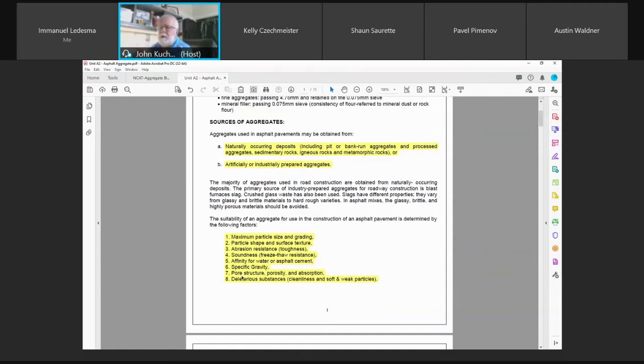In Winnipeg here, we do a lot of thin lift asphalt overlays. In other words, we peel off what we have that's on the concrete. Okay, we fix up the joints, and then we put the asphalt back in. So we're limited, maybe 60 millimeters. And that's why the type 1A mix that we're looking at is nominal size of 16 millimeter because of the thickness. So you want to go about 3 to 4 times. The thickness should be no more than 3 to 4 times the maximum size of aggregate. Okay, so that's why maximum size is very important.